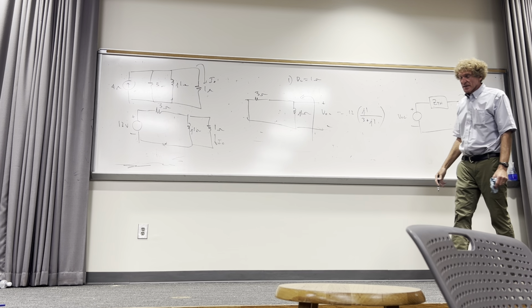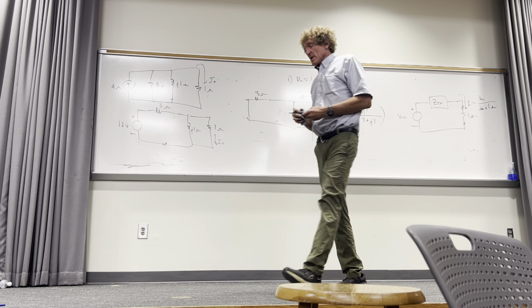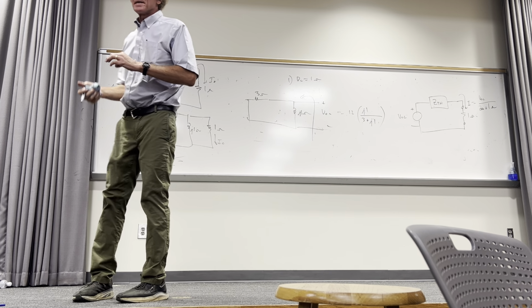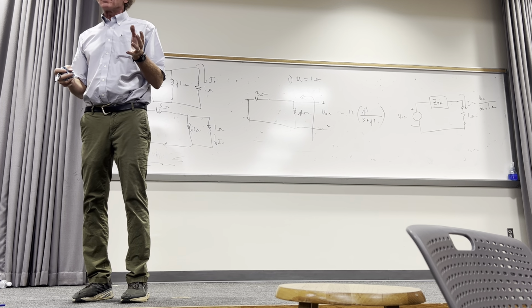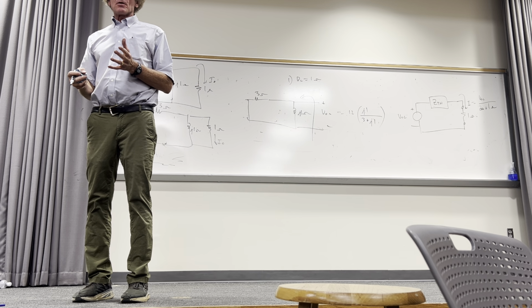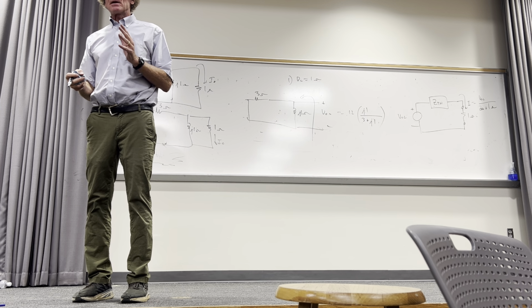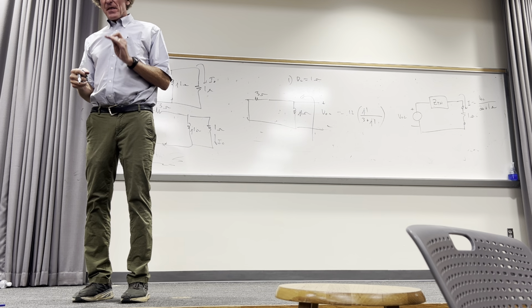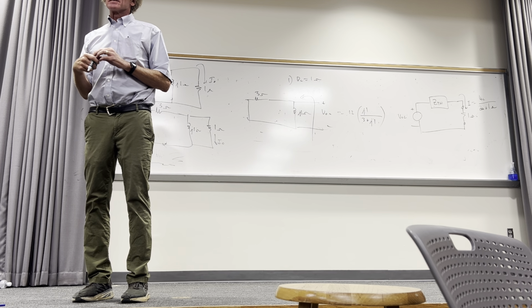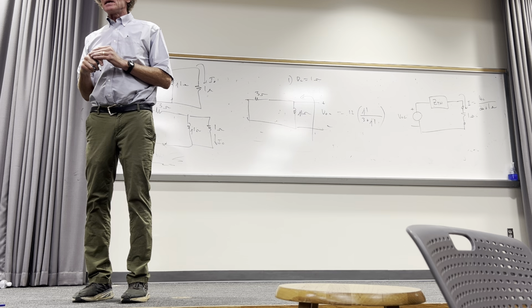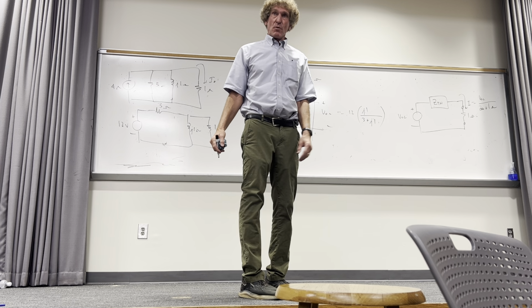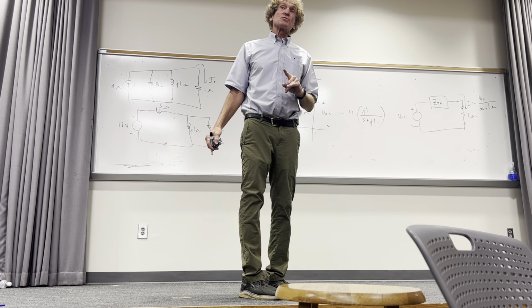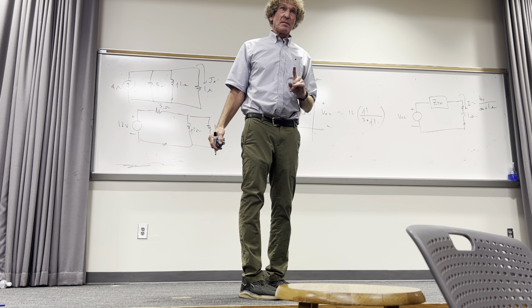And that's really it. Now, that is, in my opinion, a much quicker way to get to the result. Some of you don't like complex numbers. You will get used to them. They're not bad at all, but you do have to appreciate how to do these kinds of problems. And Thevenin analysis for this stuff is probably the easiest and quickest way to get most answers, if you want a single answer. Now, if you want the voltage and current at several different points, it's a little different, but if you just want a voltage or a current through one element, Thevenin is the way to go.